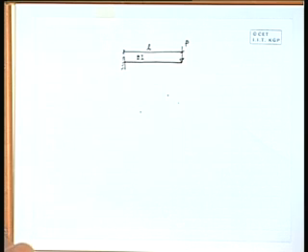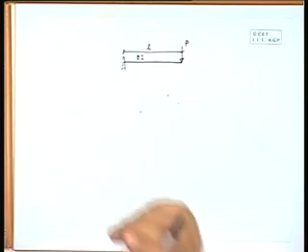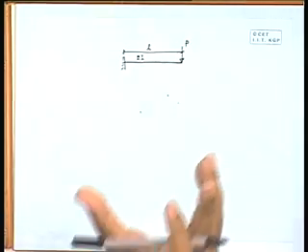So, this is a beam, left support is fixed or clamped, right side is free, at the free end there is a vertical load P, the total length of the beam is L, it has a material property E, cross sectional property is I, means its second moment of area or moment of inertia of the cross section. It is a uniform cross section, everywhere it is EI.